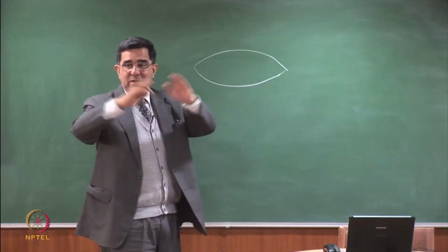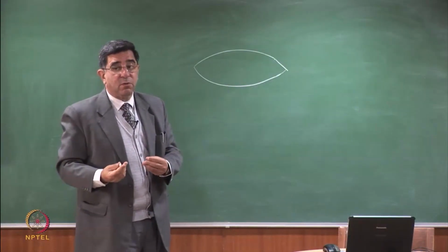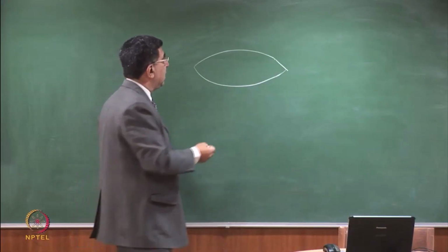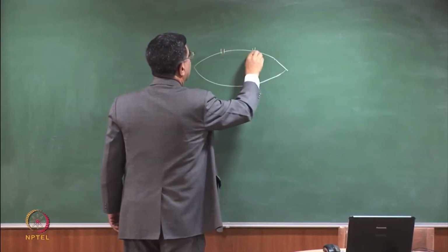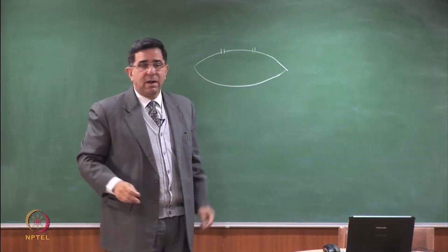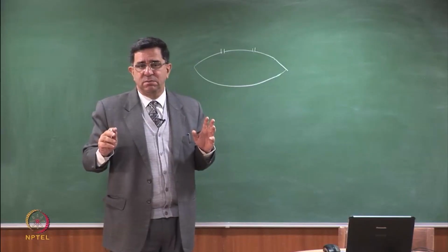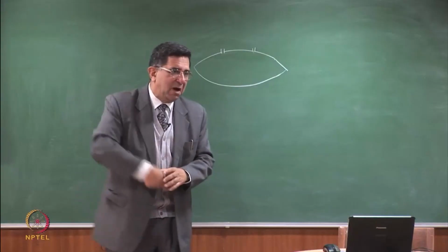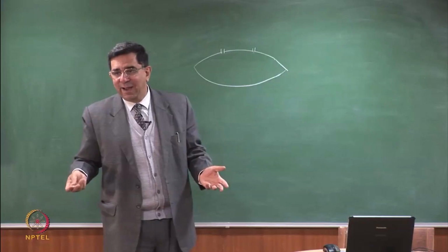If I have a well-designed containment system, and remember, containment for gas is much more difficult than containment for water, then if I have, let us say, 2 vents, gas will come out in these vents at its own pressure. This is called a passive system. But if I take a suction pump and start applying suction in those vents, I will take out more gas, that becomes an active system.